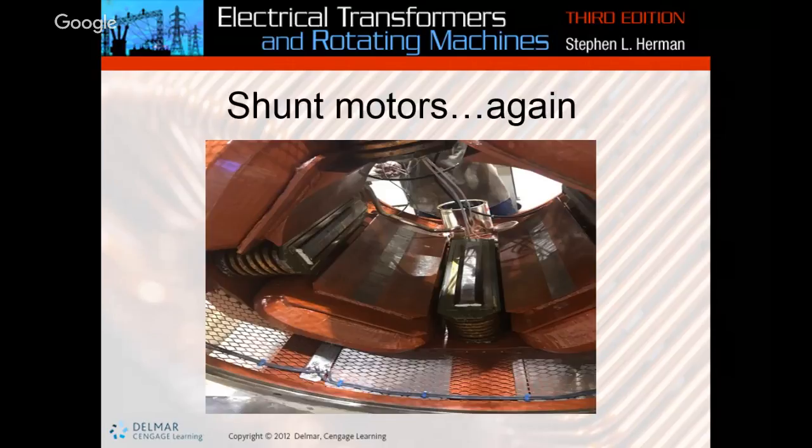But as that's happening, as we're loading, since the speed is trying to maintain itself, the way that a DC motor controls its speed is it has to increase its torque or its current. So as we're loading onto this motor, the speed is going to try to stay the same, but as the speed has to stay the same, the torque has to come up to be able to maintain that speed. So the speed is going to lead, and how I always remember that is when we're talking DC motors, voltage equals speed. Okay, so when we're talking, oh geez, I'm lagging this voltage down, now my current has to build up.